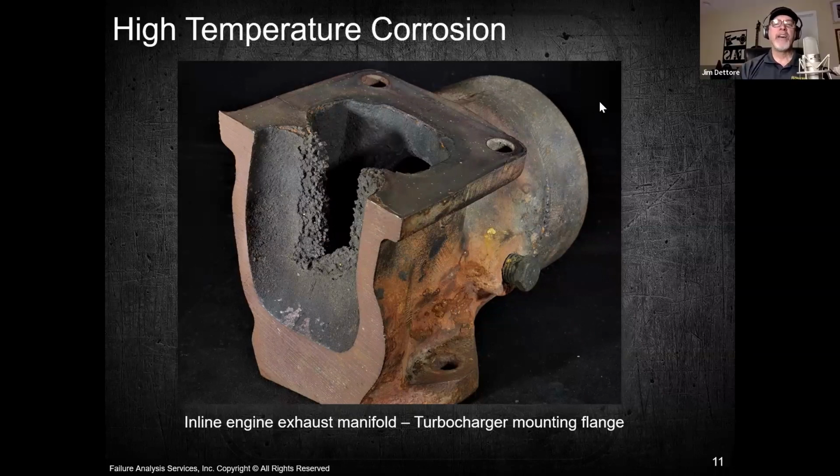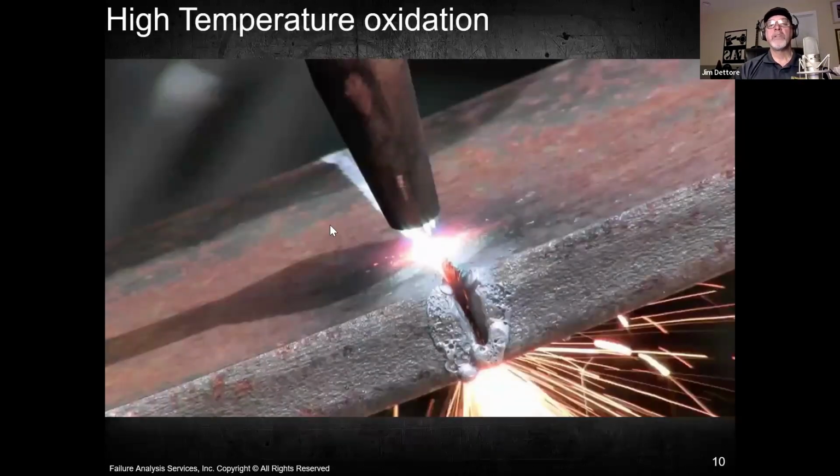So what can happen is if we have excessively high exhaust temperatures, as well as potential corrosive constituents in the exhaust stream. On the diesel side, high exhaust temperatures in here could mean raw fuel entering that exhaust manifold. On the gas compression side, we could have excessively high combustion temperatures or potential corrosive constituents such as H2S in the exhaust stream. So it heats this area up just like we did with the cutting torch, right?